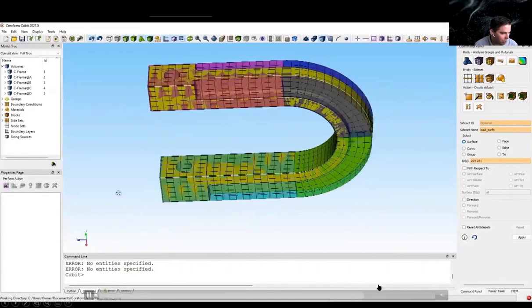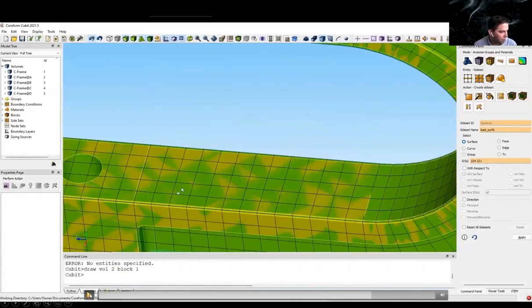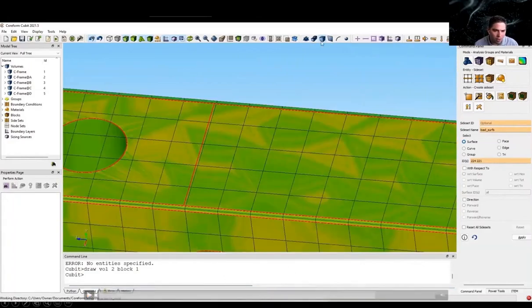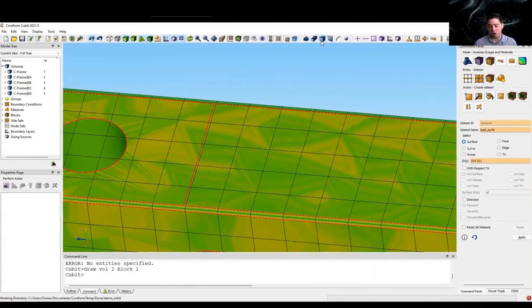We have to apply boundary conditions onto a conforming region of elements. As we can see here, as I zoom in, this finite element mesh or this computational domain does not have to actually conform to our surfaces. What this means is that we can actually change the boundaries and the shape and the size of our load regions without having to remesh.